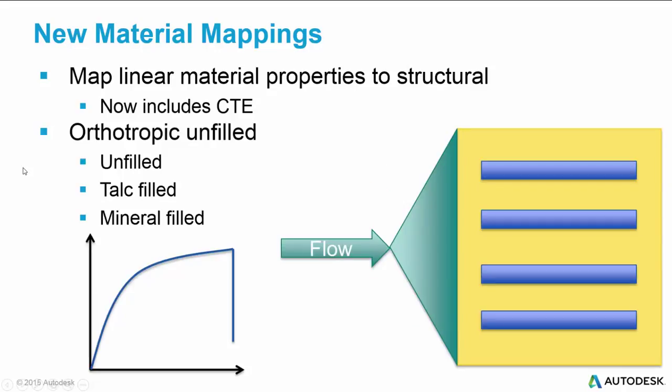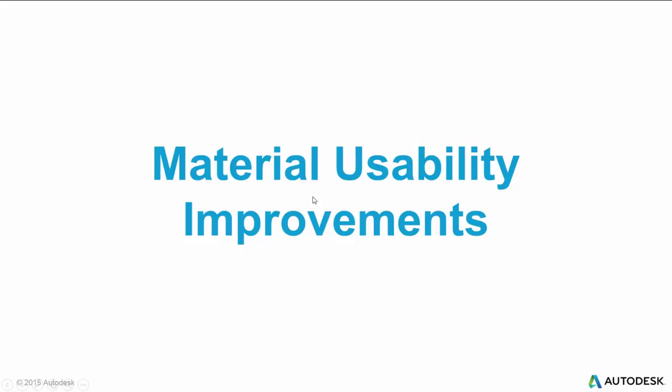We also added support for orthotropic unfilled. So before we could only do isotropic unfilled, we did not support talc or mineral. And now we support unfilled, talc filled, mineral filled. They can be orthotropic and we will map them to the structural simulation. You can do linear or nonlinear simulations with those as well.